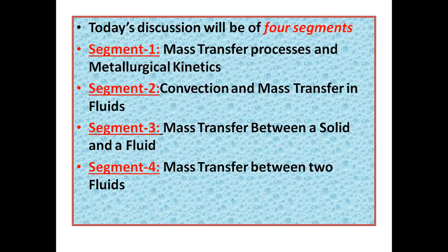When we come to steel making processes, even there, mass transfer is there. Generally, some of the elements, manganese, silicon, etc., are retained in the metal phase as impurities. In the slag phase, oxygen is there. The element is coming from this side, oxygen is coming from the slag side, and at the interface they meet together, forming respective oxides.